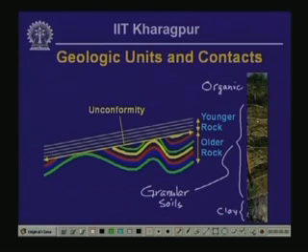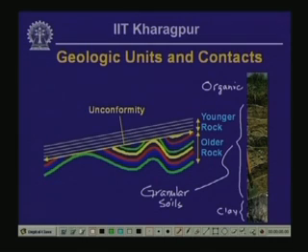So, here you have got several different geologic units. Basically you have got an organic layer near the top, and a sequence of granular soils underlain by a layer of clay. And you have to notice that the contact between each one of these layers is sometimes near horizontal, and sometimes they are dipping either to the left or to the right of this particular picture.